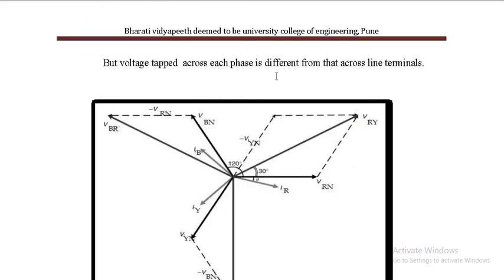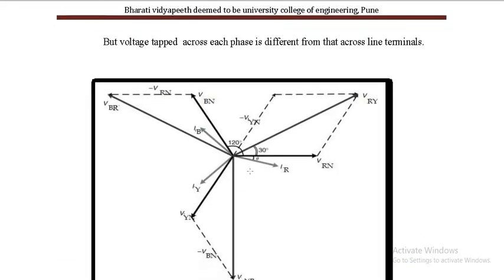You can see over here in the phasor diagram, I can draw Vr, 120 degrees behind I will show Vy, still 120 degrees behind I will show Vb. Understood? So what I did is Vrn, Vyn and Vbn are shown 120 degrees apart. Then I have to show that Vr minus Vy is going to be Vry.